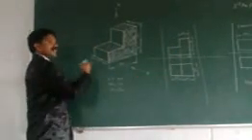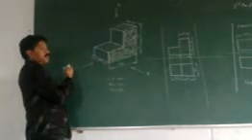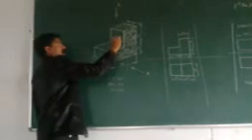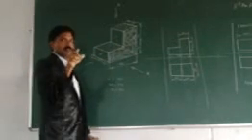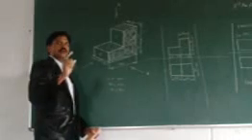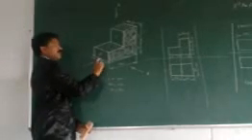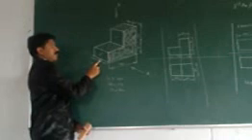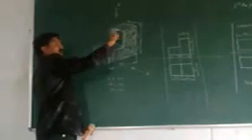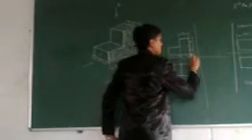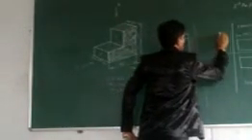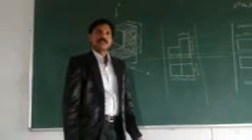And next come to the side. So when you observe from this direction, only this rectangle and this rectangle are visible from the left side direction. Why? Because in the left side view, we observe the dimensions width and height. So the width is 50 and the height is 30 and 30. See, so simply project. This is 30 and this is also 30. Total height is 60.